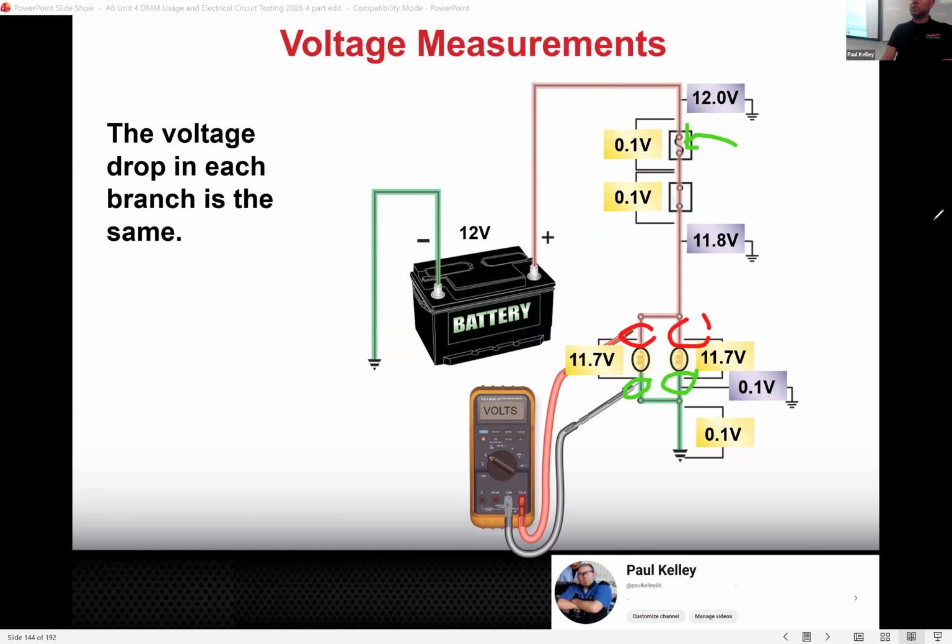First off, there's a couple different ways we could approach that. But if your 10 amp fuse is blown, that means it's flowing more than 10 amps. But how many amps? I don't know. So maybe we would measure it and be like, how many amps are you flowing? But truthfully, that'd be pretty rare, because normally when a fuse blows, it's probably because this is shorted to ground. So I'm not even sure that I'd calculate the amperage right off the bat.